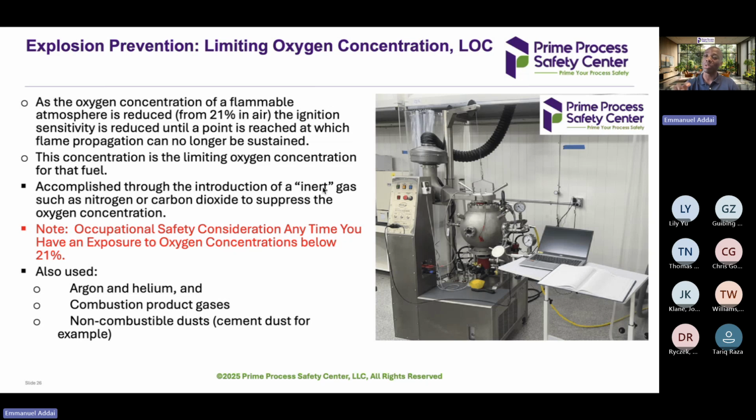Sometimes people say, okay, let me try to use, we have various bases of safety. The first one is avoidance of a flammable atmosphere, which is either removing oxygen or the fuel. And the secondary is the ignition source. But to be sincere with you, the reason the ignition source is secondary is you can never eliminate all ignition sources. So the primary one is the most important thing if you want to prevent any explosion. Number one is the fuel and the oxygen. And usually, in order to use oxygen as the basis of safety through inerting, that means you need to know you are limiting oxygen concentration.